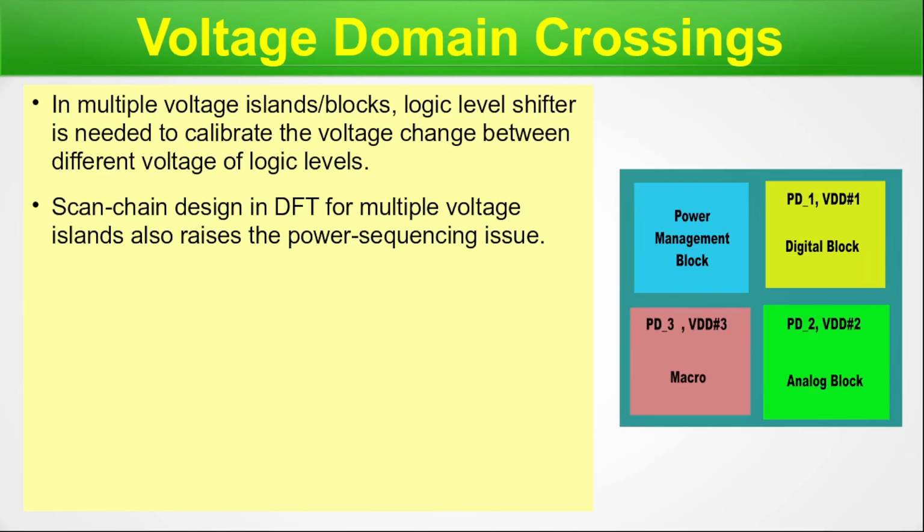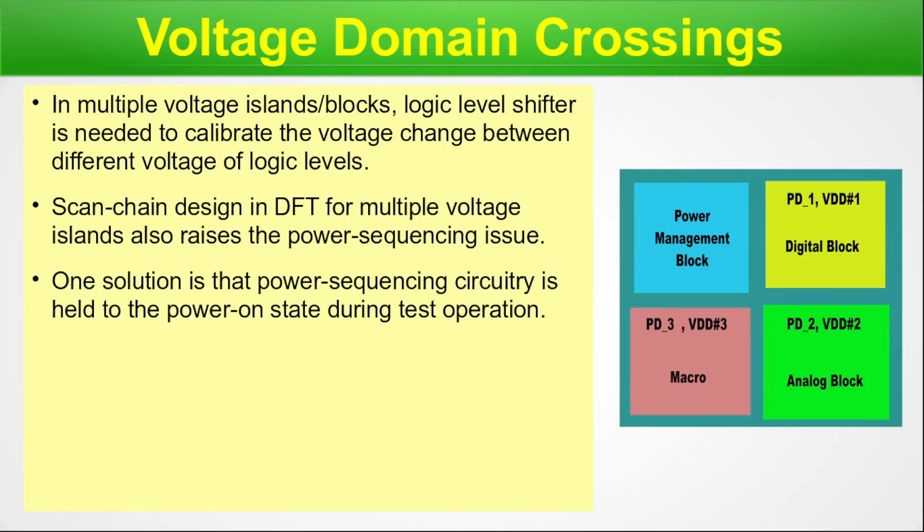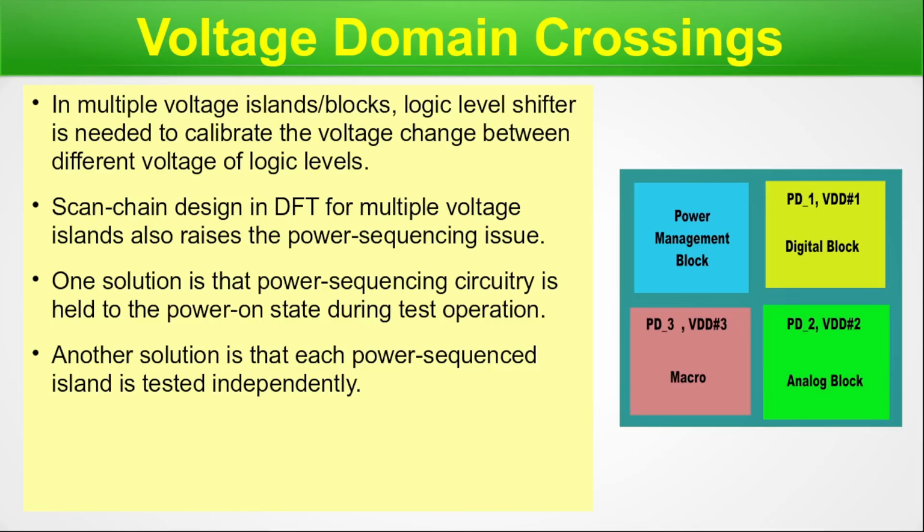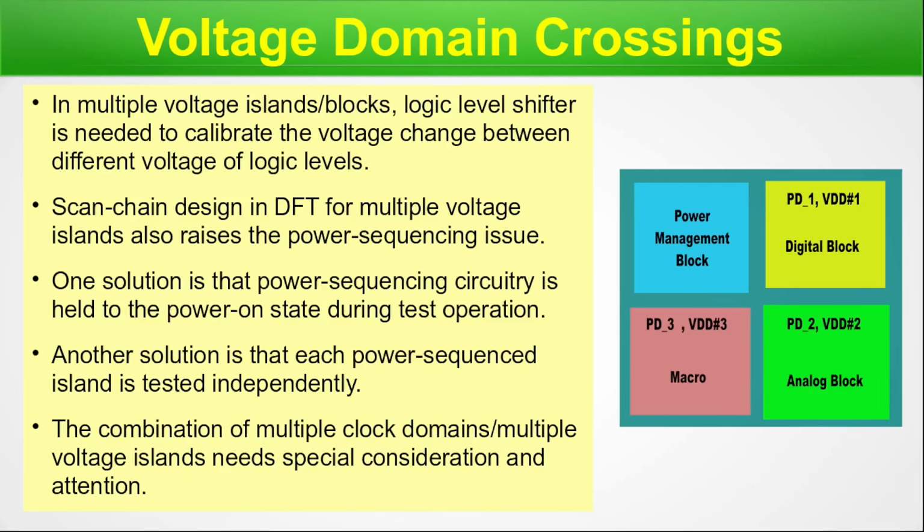Scan chain design in DFT for multiple voltage islands also raises the power sequencing issue. One solution is that power sequencing circuitry is held to the power-on state during the test operation. Another solution is that each power-sequenced island is tested independently. The combination of multiple clock domains or multiple voltage domain islands needs special consideration and attention.